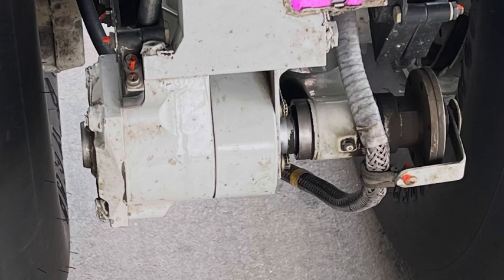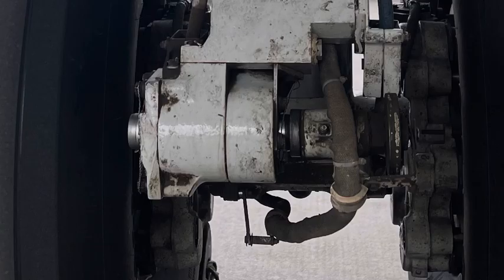In fact, some side-to-side shimmying or movement will be brought to the landing gear, so the shimmy damper system absorbs this shock. If the force is brought to the left, the piston will extend to the left in order to absorb the shock and limit it on the landing gear. If the force is applied to the right, the piston will extend to the right to absorb this shimmying.